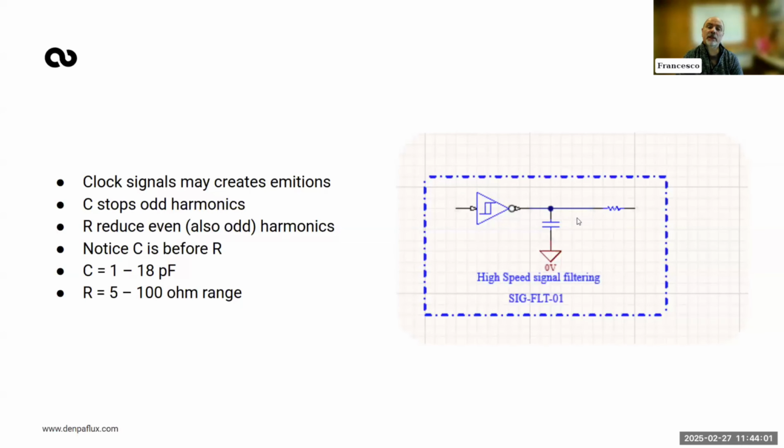So I got a solution. I use a template. On the clock side, I use a capacitor which I don't fit, but is there if I got a problem. And the resistor, which I use 0 ohm, but is there if I got some problem.